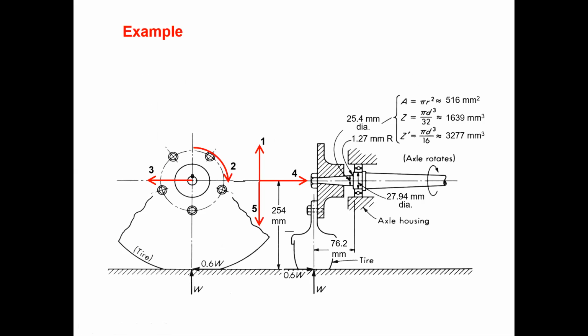Yes, then, as I told you, we need to identify what are the mean loads and what are the alternating loads in here. Mean loads you can easily understand. They should be around the axis or applied on the axis. In here, you can see load type 4, the axial compression, is applied on the axis, so that is a mean load. And this one, the same center, is applied around the axis, so that is also a mean load. It will not change at any time.